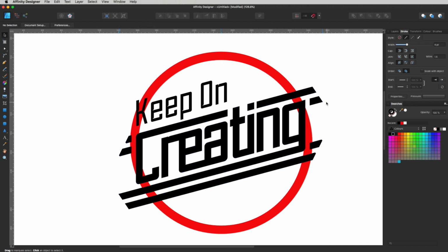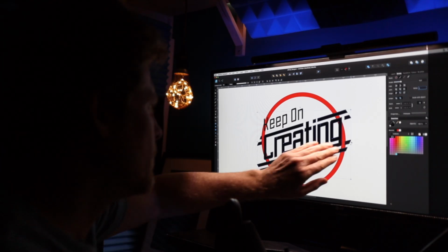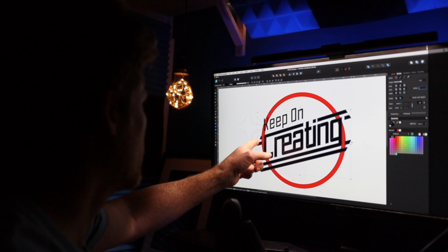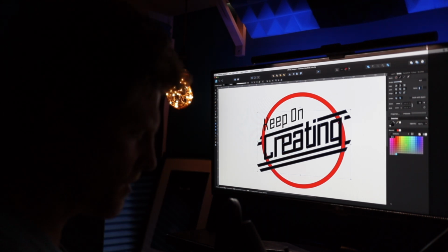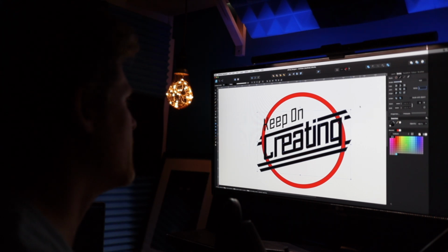You can see it's created that nice sharp edge. Let's get rid of those rulers. It has dumped them on this edge over here. If we take up our mitre, you can see on this edge over here, these little edges there, it has capped them. Okay, so if I just take up my mitre, I'm just going to bang that all the way up to like 6, and you can see it's given us our nice sharp edges again there. So that's definitely what I'm looking for.